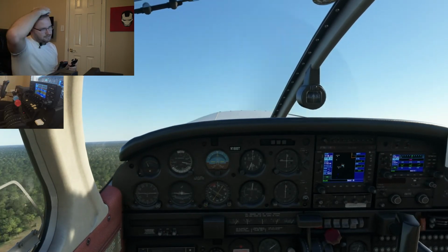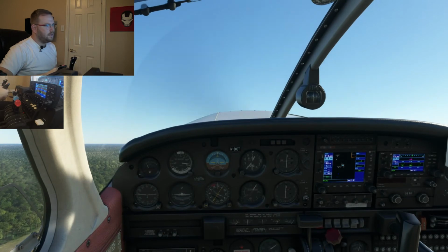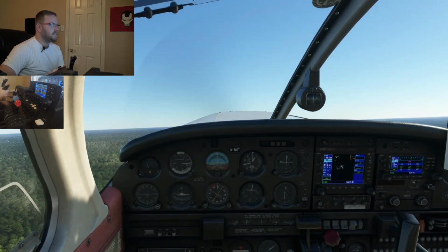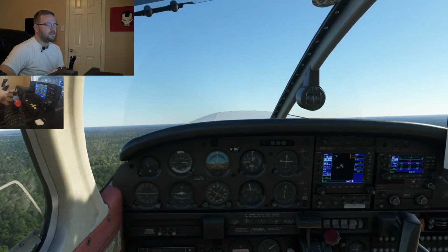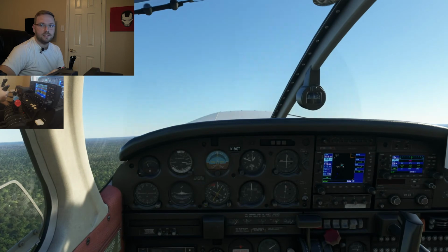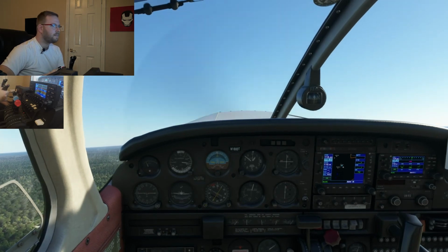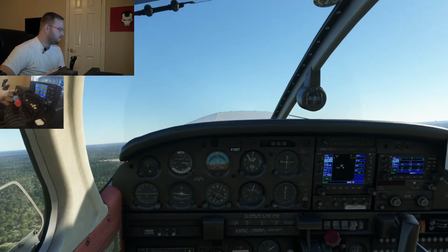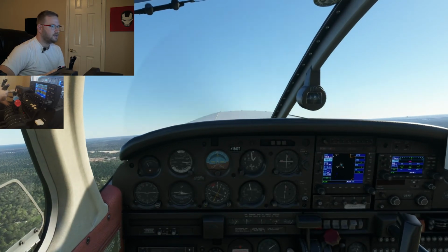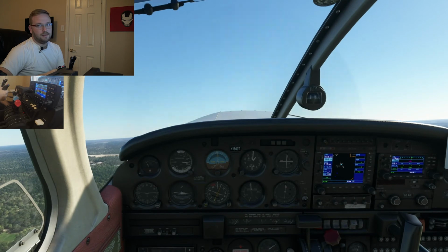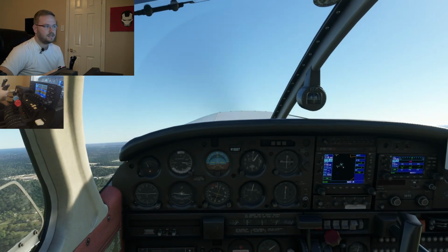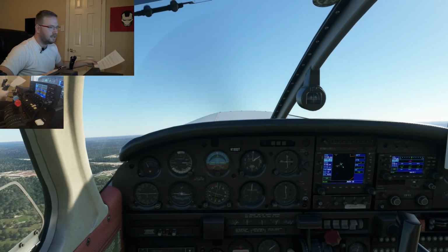So now he'd probably say something along the lines of, he being the tower, he or she, they'd probably say, Cherokee 1800 Tango, southbound departure approved, have a good day. I would say southbound departure approved, Cherokee 1800 Tango. So we're climbing up, going to climb up again to 1500, and we're going to head back to our main airport. But next episode, we're going to be doing the emergency test, the emergency procedure, and then the final landing procedure once we get there.